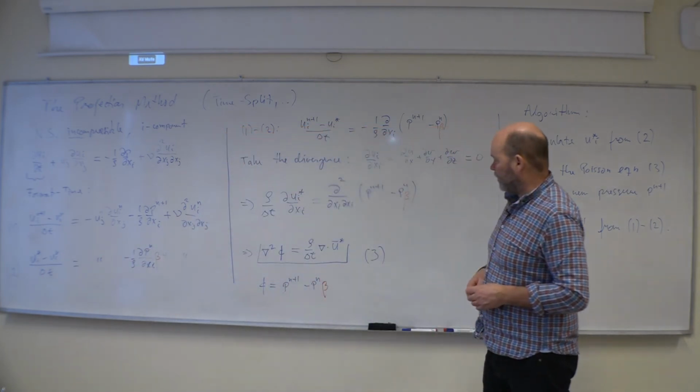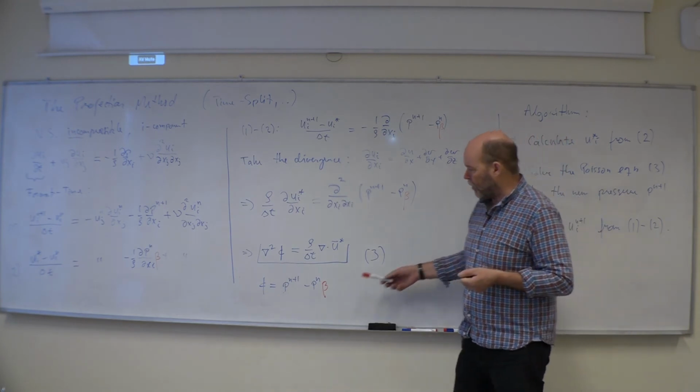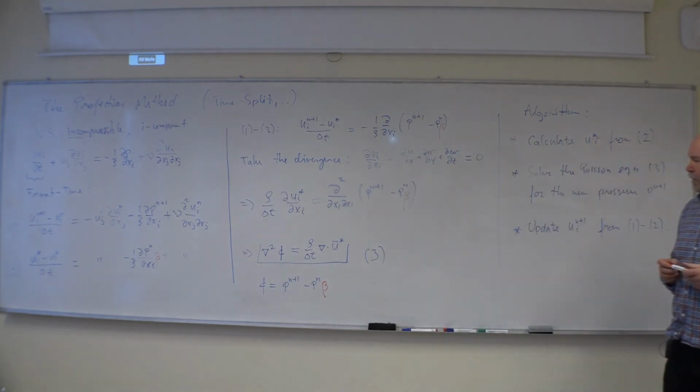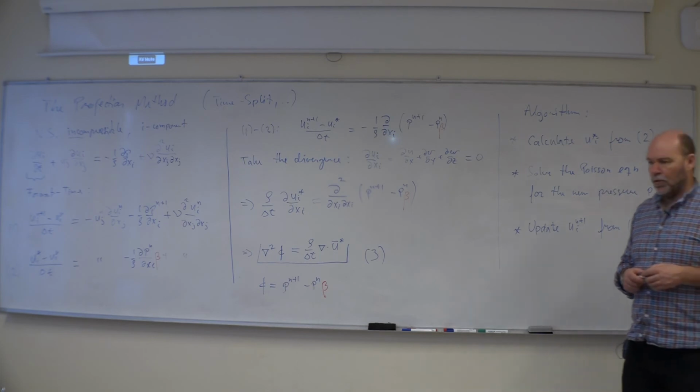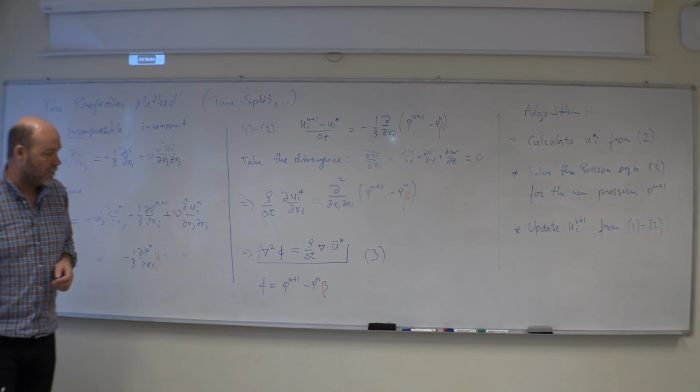And then you will have a little bit simpler Poisson equation only for the pressure, not for the pressure difference. I won't recommend it though, because in a time evolving flow, we are going to operate with quite small time steps anyway. So the difference in pressure is not going to be that big.